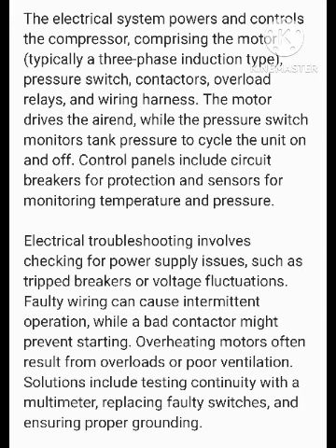Electrical troubleshooting involves checking for power supply issues, such as tripped breakers or voltage fluctuations. Faulty wiring can cause intermittent operation, while a bad contactor might prevent starting. Overheating motors often result from overloads or poor ventilation. Solutions include testing continuity with a multimeter, replacing faulty switches, and ensuring proper grounding.